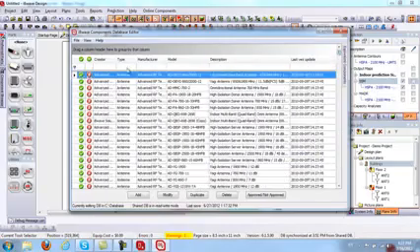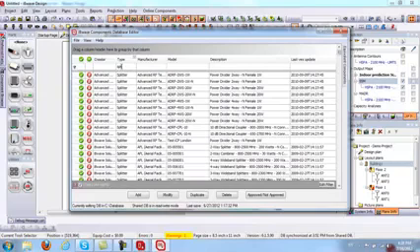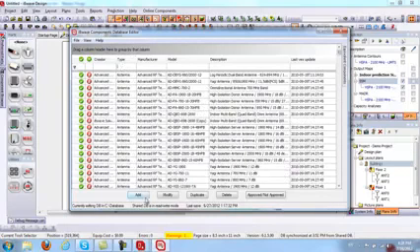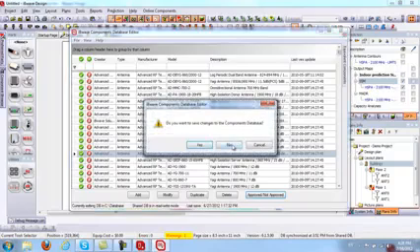You can filter by the type or manufacturer, or depending on what you want. So you can filter here for the type of component you want. Here you have the option to add a new component to the database. You can click on a component and modify it. You can duplicate the component, you can delete it, and you also have the option to select approved or not approved. So if I do approved or not approved, as you see, this turns to red here, and if I approve it, it turns to green. And this is basically for management to approve certain parts to be used by the engineers, and that way they can ensure consistency while designing and that everyone is using the same parts. So this is our component database, and I'll go ahead and close it for now.